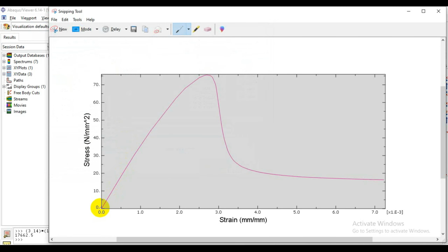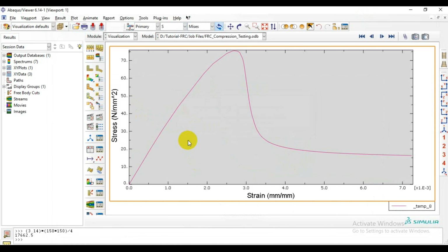So remember I mentioned these three things over here. This one up to this region it was before cracking, then it was cracking, and this region it was elastic. At this point the crack and damage occurred, while at this point it is strain hardening. So go back to the previous videos, you will find the discussions that I did.